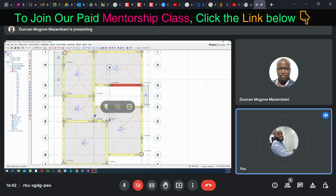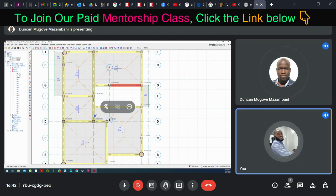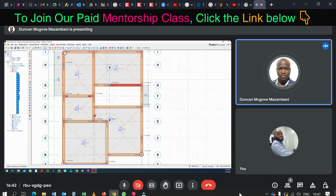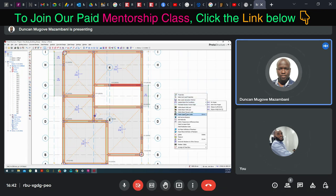Yes. On this structure tree here, where you have your beams listed, click on the first beam, hold your shift key and click on the last beam. It will select all the beams. That's fine. Now come out, right click and say paste copied beam wall load. Paste, yeah, that's fine.